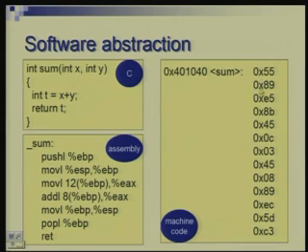So, each step here is essentially a number. The number notation I have used here is hexadecimal. This 0x indicates that the number is a hexadecimal number, which is nothing but a number to the base 16. So, 2 hexadecimal digits would mean that we are talking of an 8-bit number, or a byte. So, essentially it is a sequence of bytes which represent this same program, and in turn it represents this program which is originally written by a programmer.